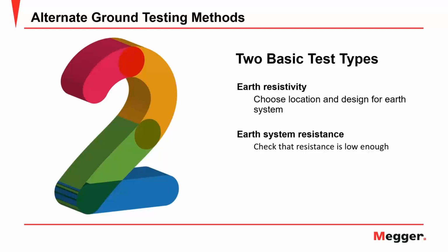And so resistance is the capability of a grounding electrode. And by that, we mean anything from a rod to a quarter-acre grid. They're all pretty much the same. It's just more metal in the ground for the purpose of establishing a low resistance electrical contact with the soil.